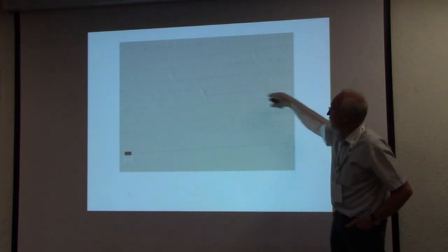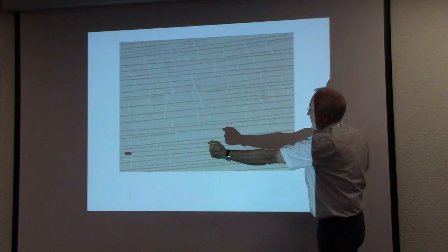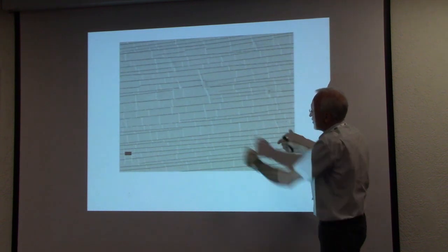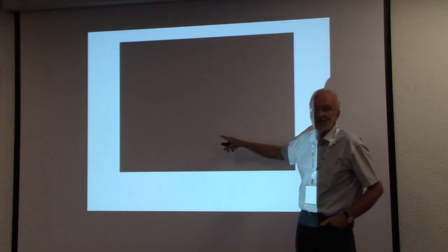Yes. So you see here the formation of the cracks. There's a tension loading in this direction. The density of cracks becomes higher, but the compliant polymer has a contraction in this direction. And this causes then the formation of these buckles, yes?